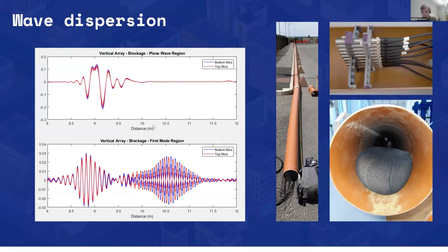You look at the distance, which is the time multiplied by the sound speed in air. That's the amplitude, and you can see the signal actually reflected from an artifact, like a blockage. It's very simple. But as the frequency of sound increases, further away from the point where the wavelengths become comparable to or smaller than the pipe diameter, the complexity of the signal increases proportionally. And then it depends where you put the microphone. If you put the microphone on the top, for example, you get the red lines.